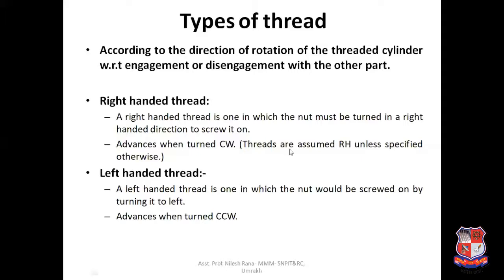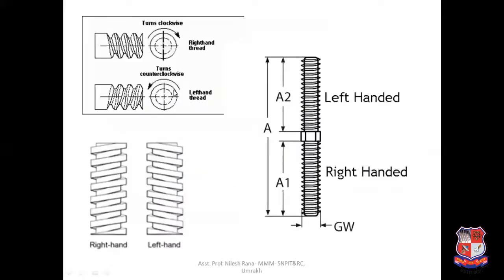Threads are assumed right-handed unless specified otherwise. A left-handed thread is one in which the nut would be screwed on by turning it to the left, so it advances when turned counterclockwise. You can see the figure of the right-handed thread and left-handed thread.